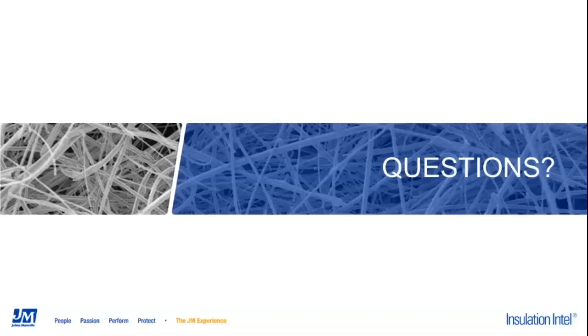We don't recommend respiratory protection with the N95 dust mask unless you're going to have fiber concentrations greater than 1 fiber per cc, and that's a weighted average over an 8-hour shift. And that's the concentration that is basically promoted by OSHA, as well as the fiberglass insulation industry.